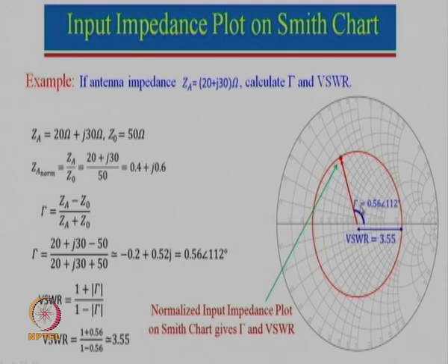Our next part is to locate this impedance. 0.4 we located over here, and then you move along this, since it is plus we need to move up. So, we move up and up, and you stop at a point; these are written here, 0.1, 0.2, and so you stop at this point. This is the point which is the normalized impedance plot.